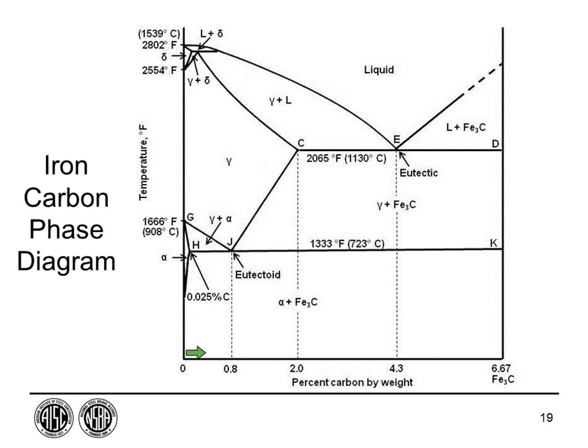What's unusual about this phase diagram is that sometimes you've heard of phase diagrams where you're just talking about liquid and solid phases. Well, these are different solid phases that occur at different temperatures and make the properties of steel rather unique. At this chemistry, it goes completely from a liquid into a solid right in one temperature range, and this is called a eutectic point. Down here we have something that looks like that, but it's a solid phase going into two solid phases, and this is called a eutectoid. This will become more important to us.